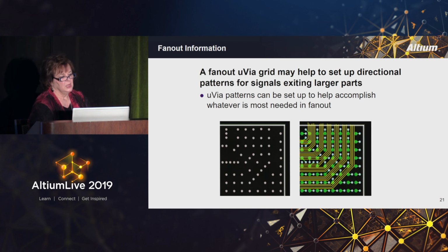Here's another one where you have a large complex BGA, and the microvias were set up into a weird-looking pattern, which allows for a lot of routing to get signals out of the interior of that part. So you can set up however you want. You just sit and play with it and study it, and things will fall into place. You just have to practice and figure out which one works better for you.